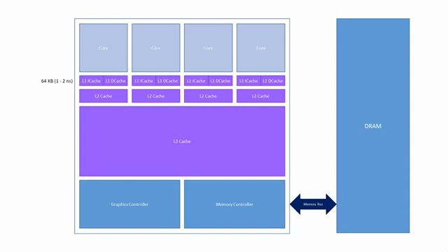This allows instructions and data to be accessed independently, making the level 1 cache even more efficient. Furthermore, the level 1 data cache has to deal with read and write operations, but the level 1 instruction cache only needs to handle reads, allowing for simplified circuitry. Each core has its own level 2 cache, which is shared by instructions and data. A typical capacity for the level 2 cache is 256 kilobytes. The access time is between 3 and 4 nanoseconds.